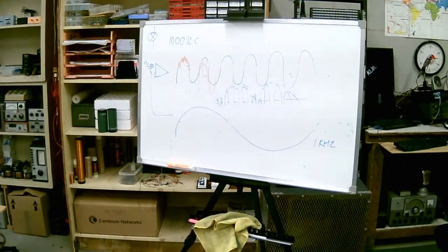Okay, so there's the audio. See, the whole top one way. We've just got the bottom now. And then this is connected to the modulator. Okay. And now you could hook up a speaker and you would hear just a tone, of a sound that's at 1.3 kilohertz. Whatever that sounds like. Something like that.